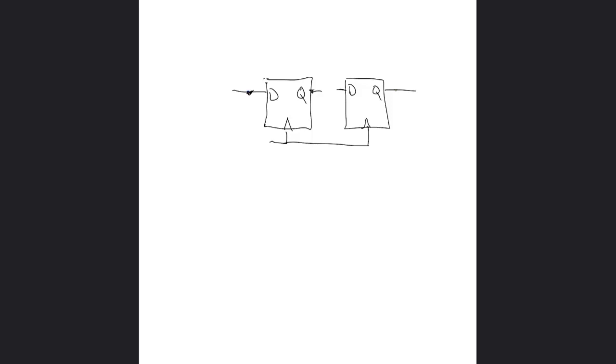No worries. So what we then do is we add a multiplexer. This multiplexer is just saying, rather than always shifting, I want to sometimes be loading my shift register in one go, all the parallel inputs. So we're adding a multiplexer here with a select line that's common across all the flip-flops. And it says, either I'm shifting, so I'm taking all these values as it was just now.